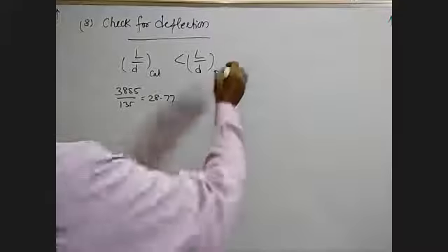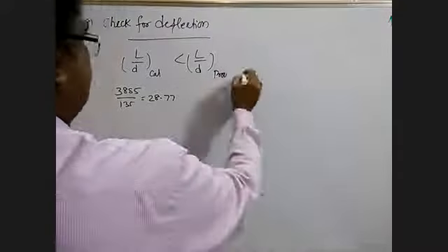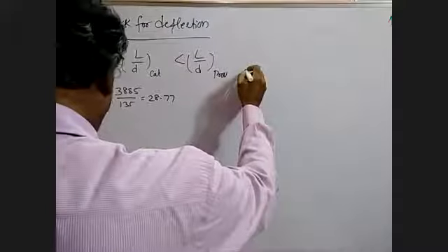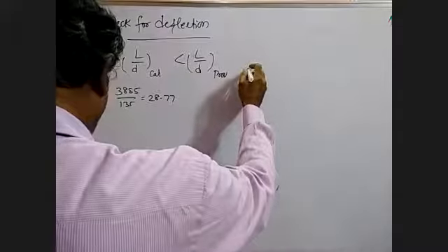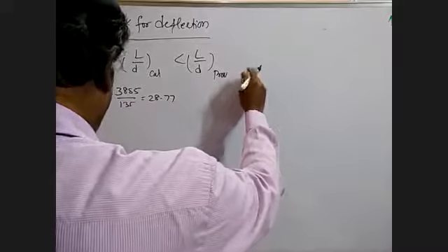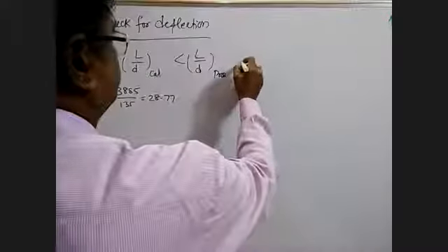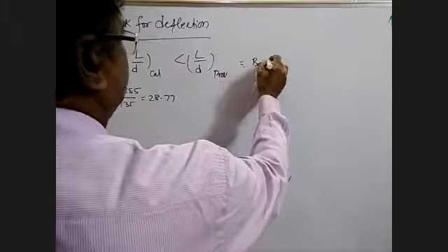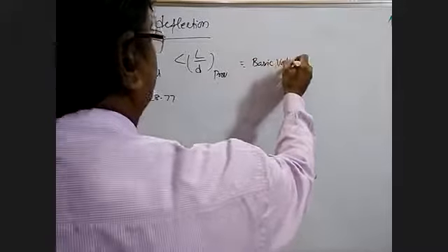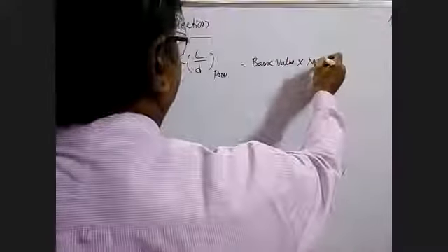Now we have to calculate this L by D provided value here. It depends upon the basic value into the modification factor.